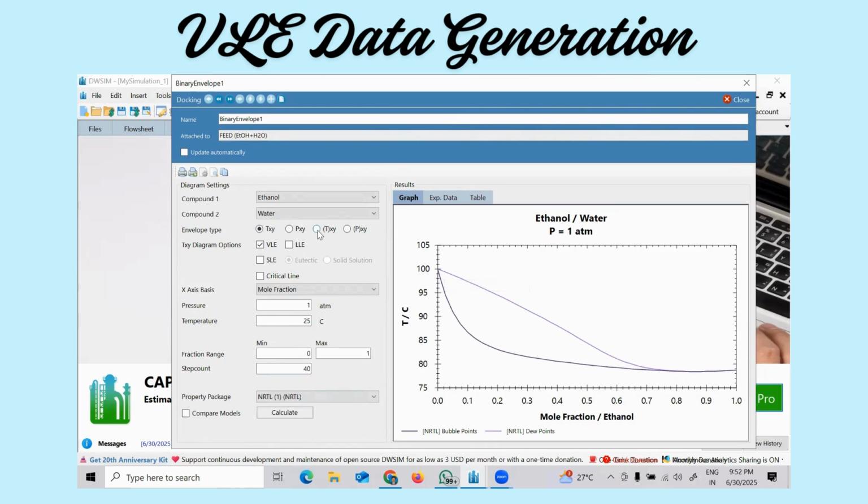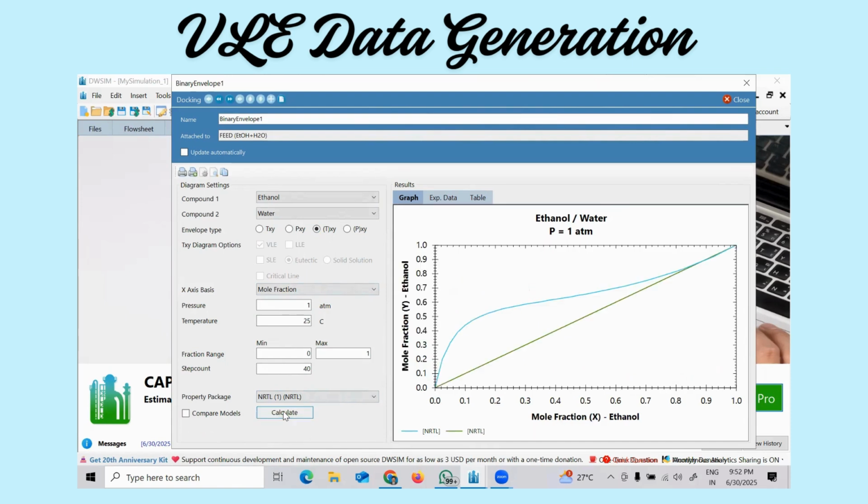Now, if you want to generate the XY diagram, same thing, let us see if it is able to calculate. Now you can see calculated. Now see, there is a small demarcation here. Now you can find that at one particular point, the mole fraction of ethanol in the liquid phase as well as in the vapor phase is 0.875, which is beautiful here. Now we can understand through the NRTL model, we are able to generate vapor liquid equilibria.